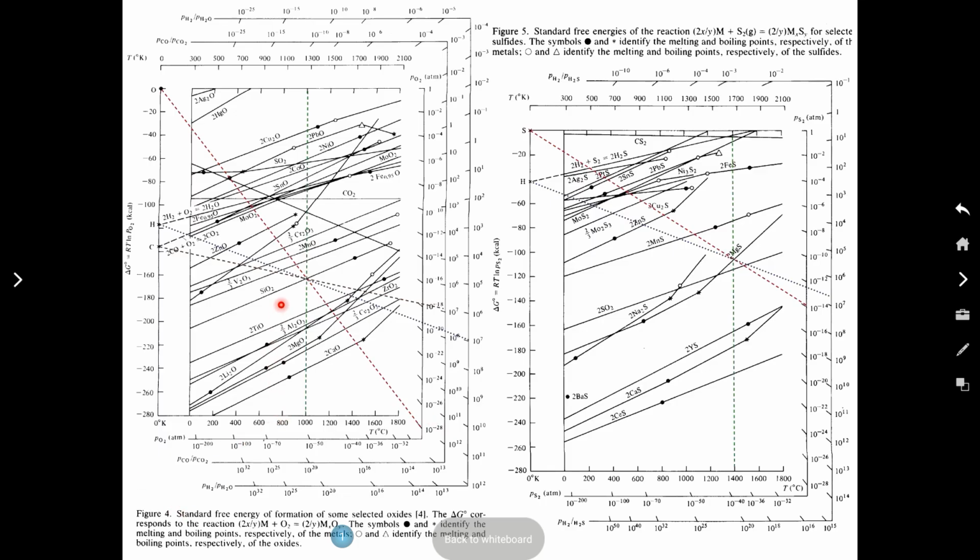So if you're doing it at 800, you'll be going through a different intersecting point that will give different values, and likewise at high temperature. So those are two knobs. Typically, you fix the temperature depending on what furnace you're using. Obviously, the higher the temperature, the faster the kinetics will be. So you want to go to the highest possible temperature and then turn the CO2 knob. That's much easier because the CO/CO2 knob can be controlled by mixing ratios, which you can change.